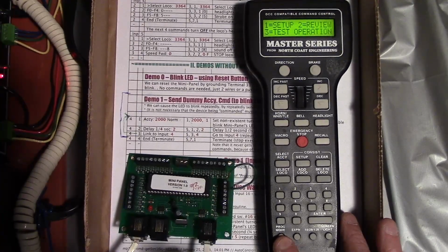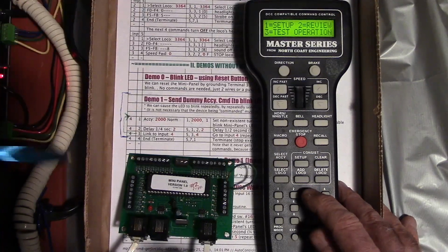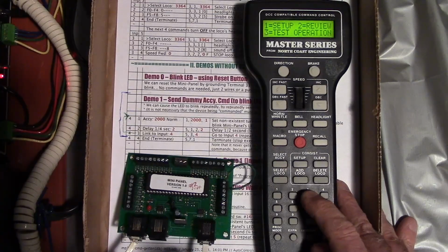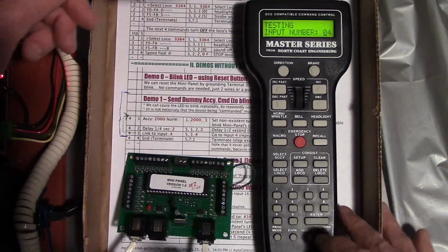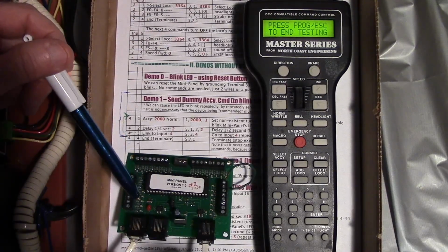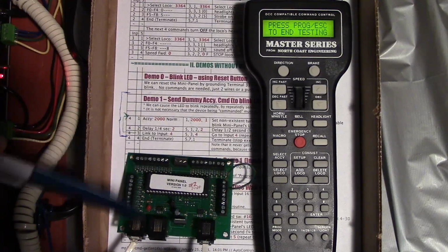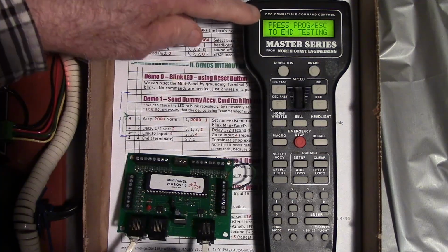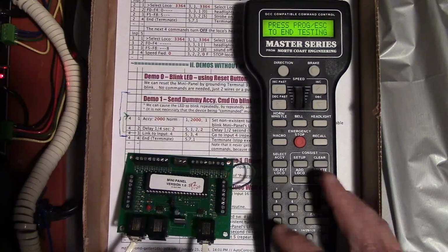So now we'll back out to the main menu. We'll push test. That's 3. Making sure our program jumper is on 1 pin and not 2. So I'm going to say test operation, input number 4, and you can see there we're getting the blinking. So that's executing that 3-line program called an automatic blink. Now there's no way to gracefully end that. It says press program escape to end testing. Well, you push it and it just ignores you because it's busy working.